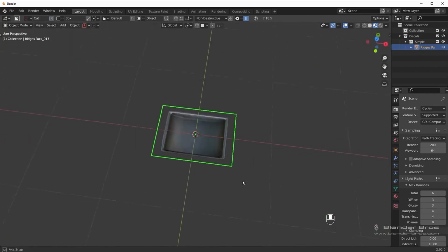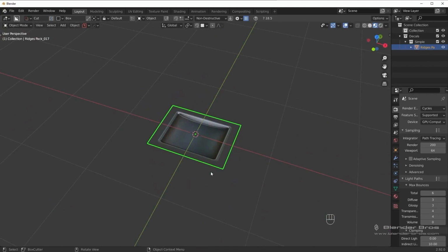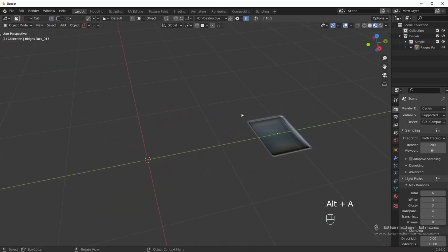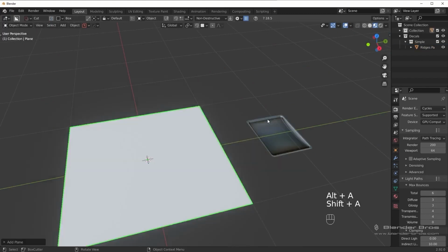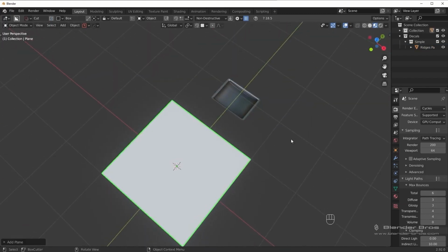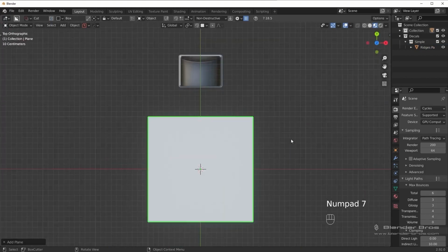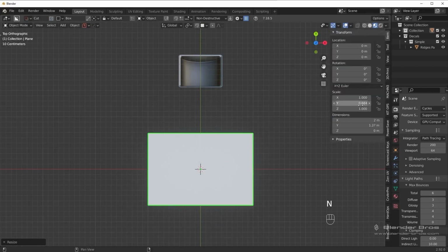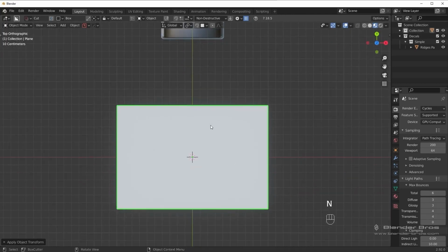Alright, so first things first, what I think I'm going to do is just move this over so that way I have reference to that one, so I'm making the same one. We'll just start with the plane on this one. This one will be really easy to do actually. So we'll start with the plane, perhaps we'll scale this a bit on the Y. Doesn't have to be super big or anything. And make sure you apply your scale whenever you scale something, very important, just so that way when you run a bevel it's not biased or anything. Even though HardOp should apply it by default, but I always apply it to be safe.